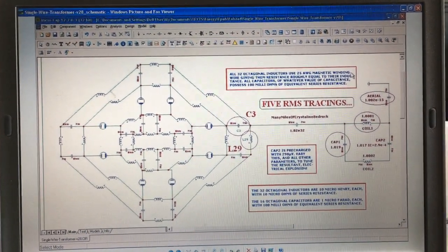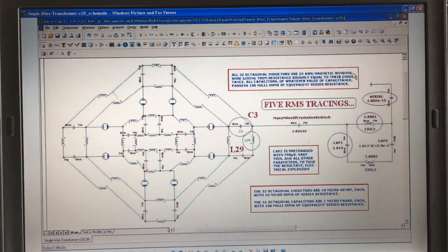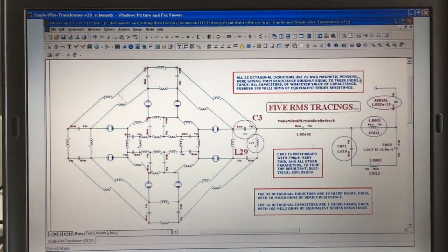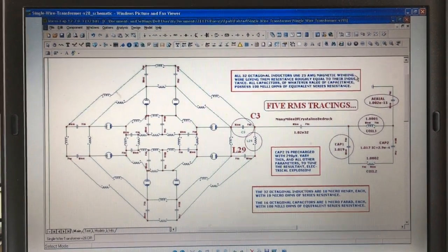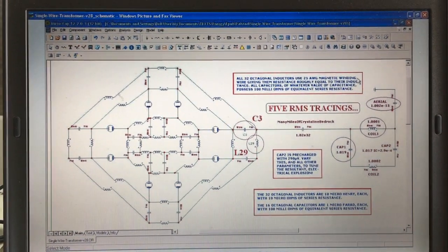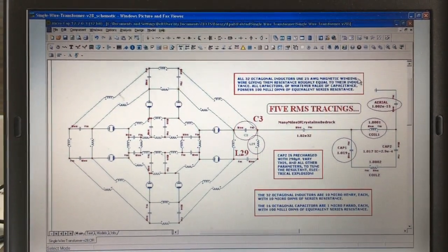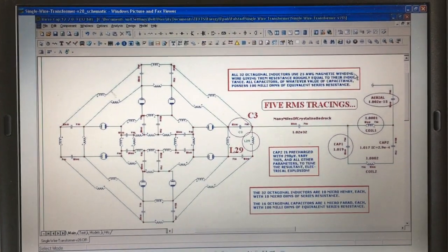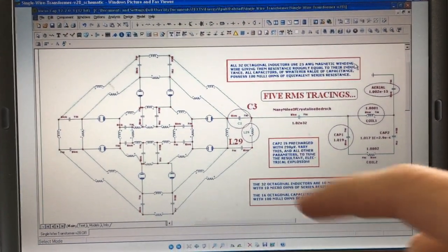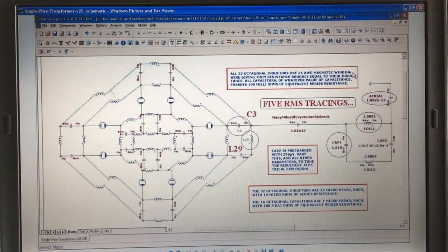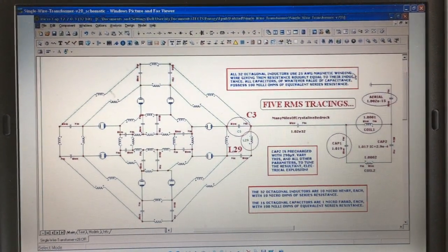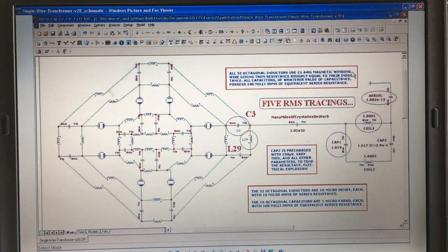The longer the duration you take it, the larger the amplitude of the current and the voltage becomes, and before you know it, you get a matrices singular error, sometimes earlier rather than later, depending on how poorly you design the circuit. So I go into each one and I modify the values of, I did it for the